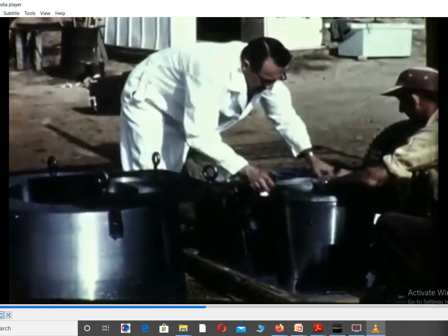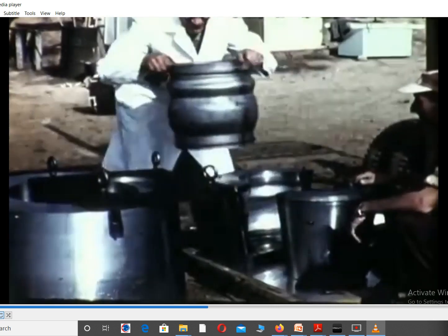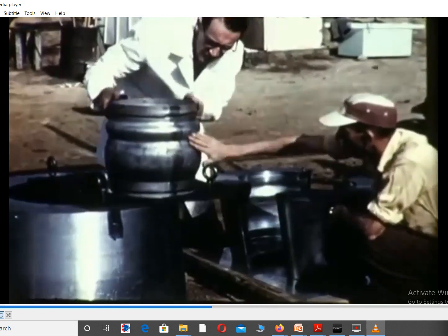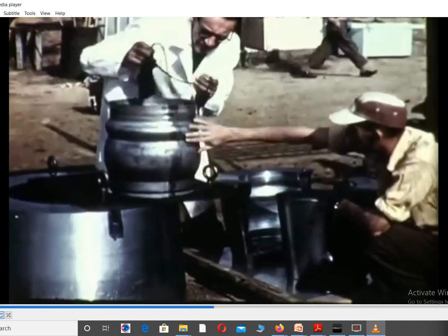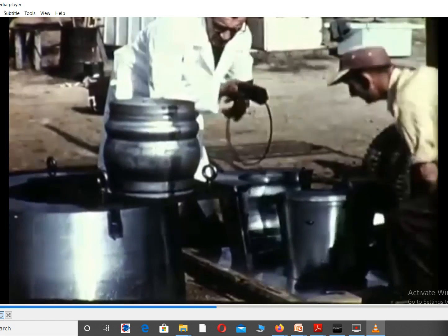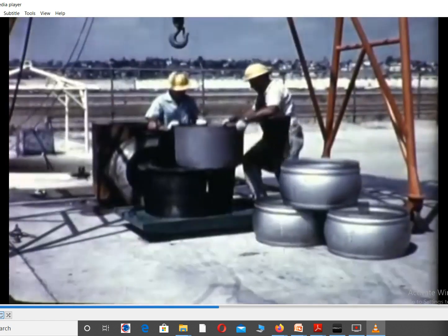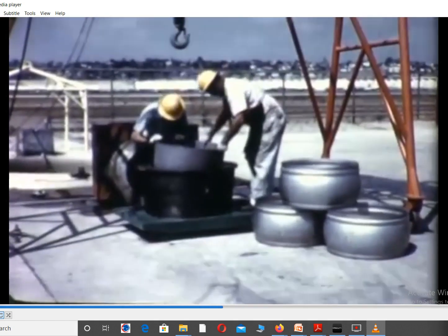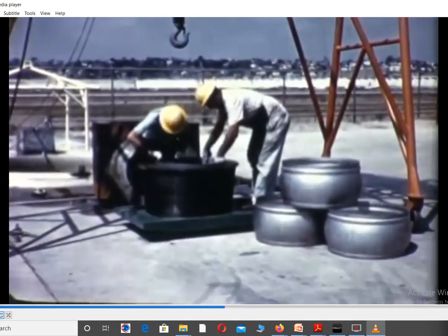Initially the sheet metal was of the same conical shape. This one was kept inside, and after the process you are getting the particular shape. The die shape you'll get. Correct. So this is what is happening in an explosive forming.